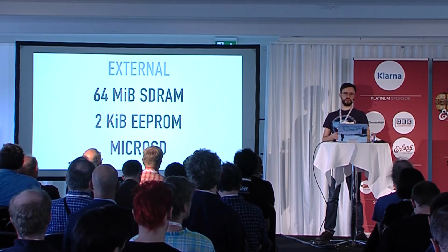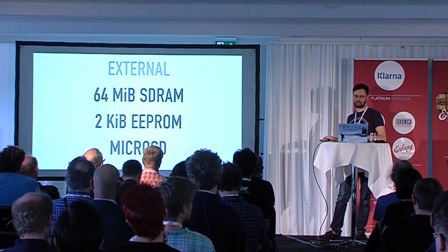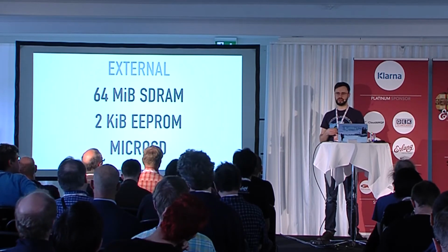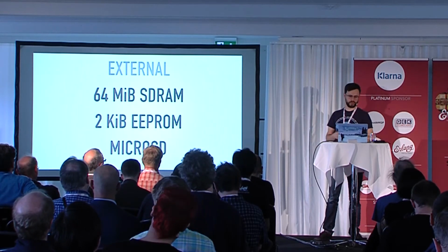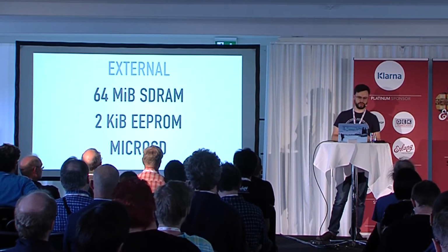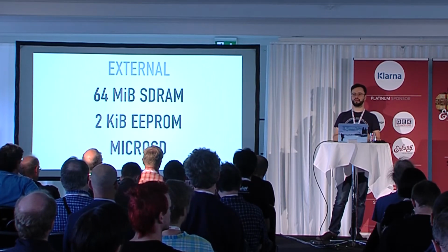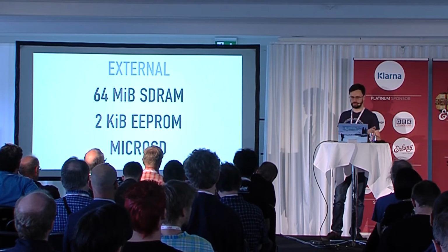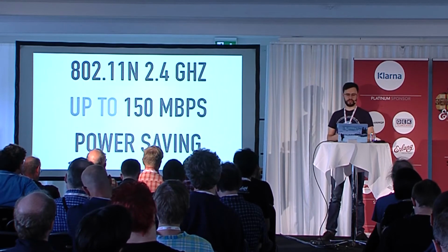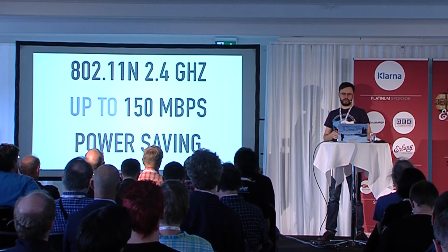We have EEPROM storage for configuration or other things. So this actually survives power outages and reboots and so on. So if you want to store some configuration, for example, if you want to provision devices and then send them out to the field, this would be a good place to do it. And of course, the micro SD slot for external storage. This is where we boot everything. The bootloader goes into the micro SD card, reads an ini file, and then boots whatever you tell it to boot.